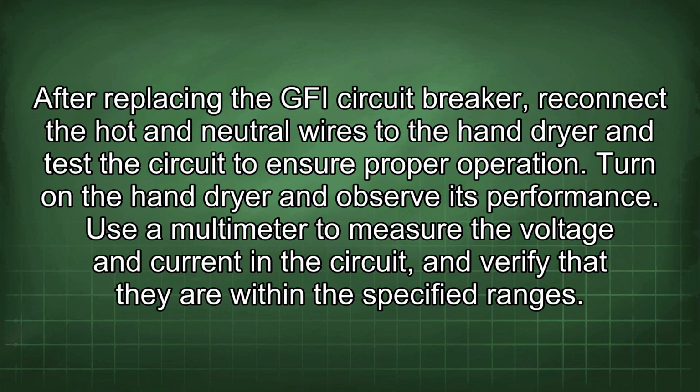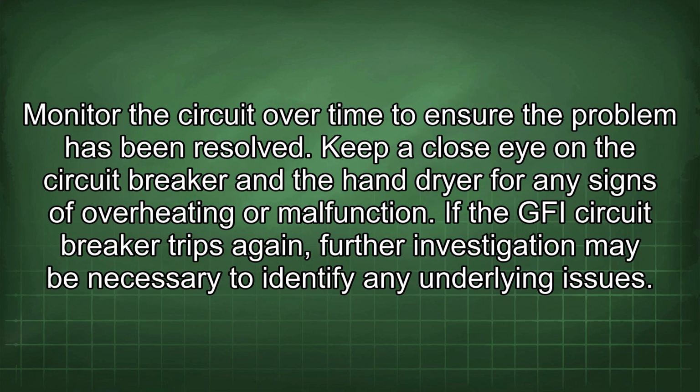After replacing the GFI circuit breaker, reconnect the hot and neutral wires to the hand dryer and test the circuit to ensure proper operation. Turn on the hand dryer and observe its performance. Use a multimeter to measure the voltage and current in the circuit and verify that they are within the specified ranges. Monitor the circuit over time to ensure the problem has been resolved.